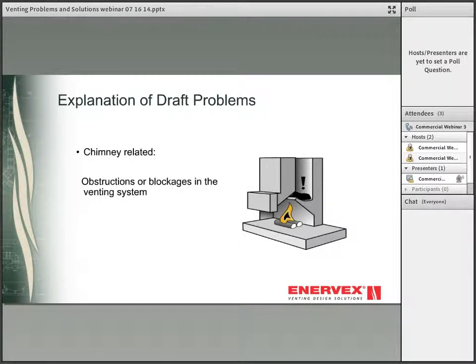A chimney can be obstructed by debris such as leaves, mortar left over during construction, or an animal or bird building a nest. Creosote buildup could also be blocking the flue or the chimney cap. Blockages might occur in deteriorating chimneys if parts of the interior collapse. This problem can occur when the flue liner is deteriorating, or if bird nests have been built outside of the heating season.